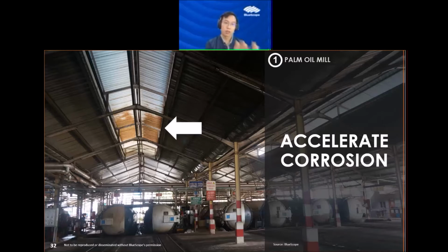So it will start with oxidation. It could be white spots, then it will eventually become rust, as you can see from this picture. In this picture, you can see the rust only happens on places directly above the sterilization chamber. That means when the chamber is open, the steam is released upward, and these are the evidence of the location where it condenses.